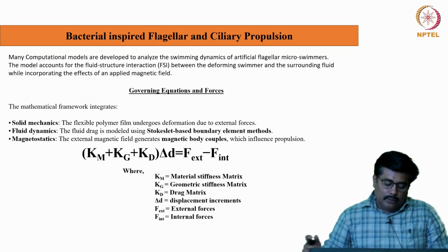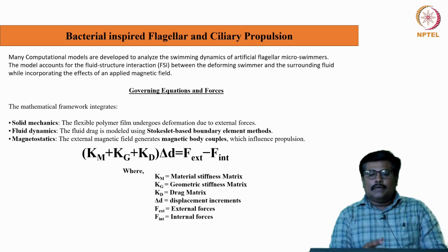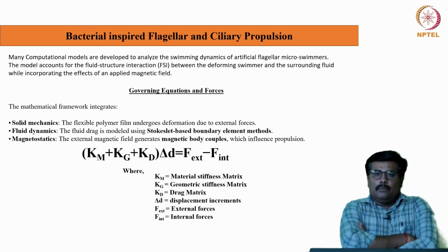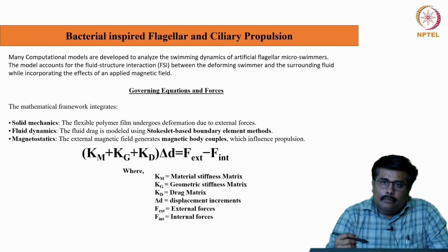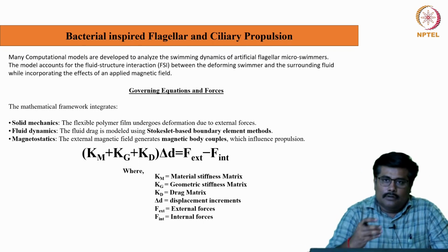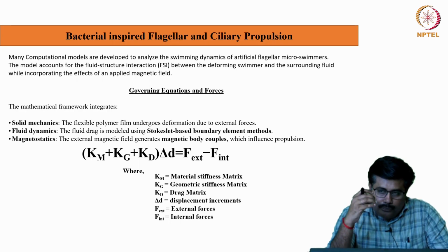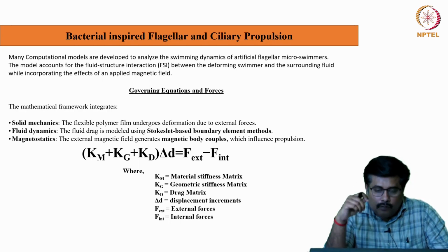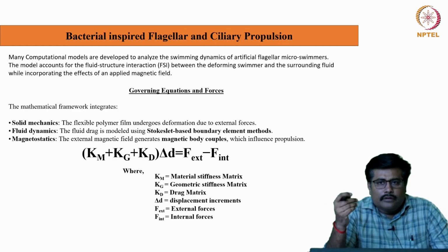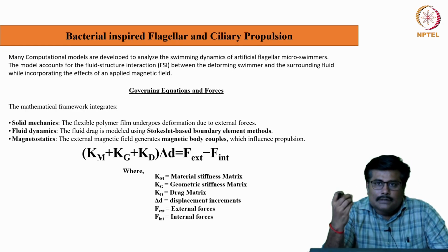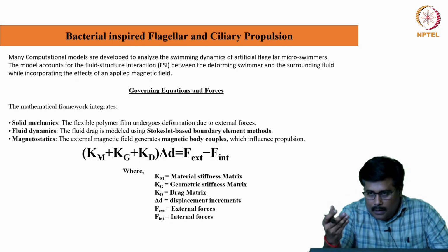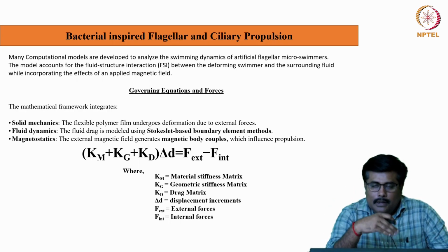Now, from the overall design point of view, many computational models have been developed to analyze the swimming dynamics of these artificial flagella, because if we think about a whip rotating at a high frequency of around 100 hertz, we need to understand the parameters involved and translate those parameters appropriately for our micro robotic system.